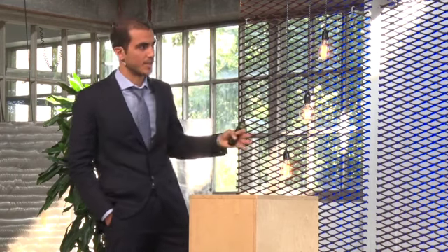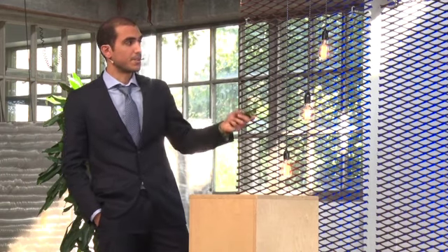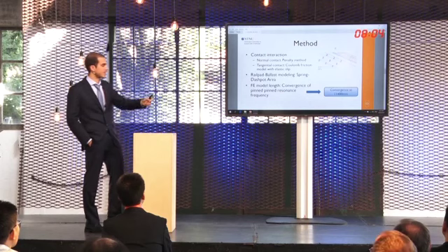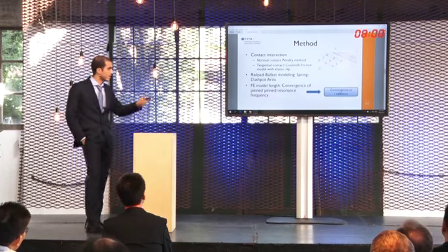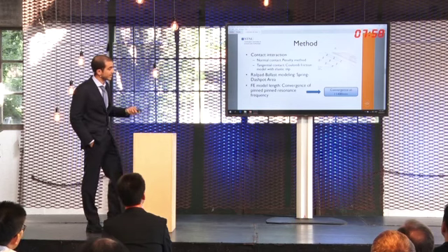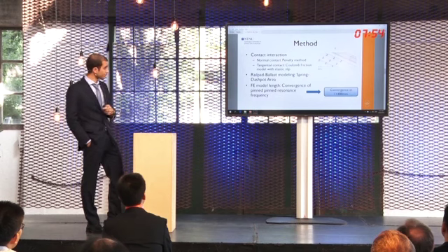For what regards the rail pad and the ballast modeling, we have used springs and dashpots in an area distributed way, while the finite element model length has been determined by computing the vertical receptance of the rail at different lengths and considering the convergence of the pin-pin resonance frequency, leading to an acceptable convergence at 11.4 meters.